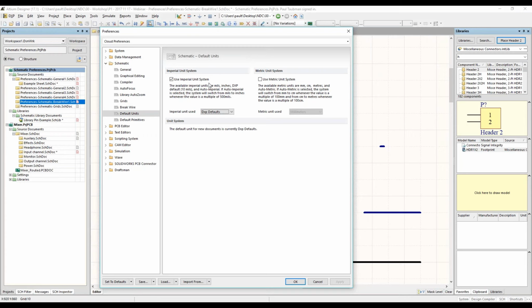One recommendation I'll make, just as a side note, is that you don't want to keep jumping back and forth, because you're going to start getting rounding error creep in your design, and that's not going to be a good thing. So nevertheless, on the schematic side, it's dimensionless. Stay with the DXP units. Everybody's got libraries built in them. It's probably the easiest thing to do.